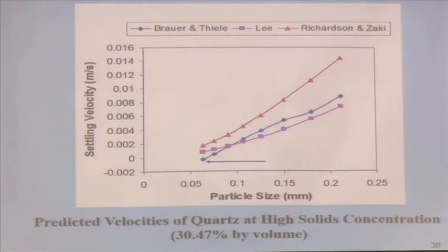That is another reason, because I can correlate it with my practical applications, and this is what we observe, isn't it? It does not matter how much flocculant I add, the big particle will become bigger also. So the best thing is to segregate it into two different sizes and treat them in two different chambers, rather than putting more reagents into one chamber. From a fluid mechanics point of view, this type of problem may come, and the problem may be because of this.